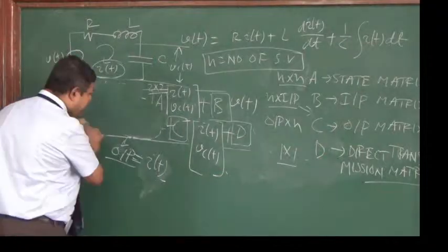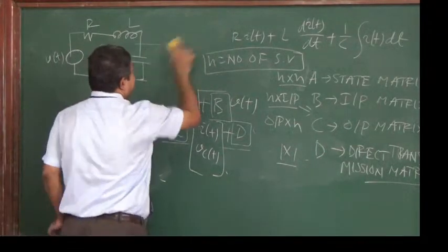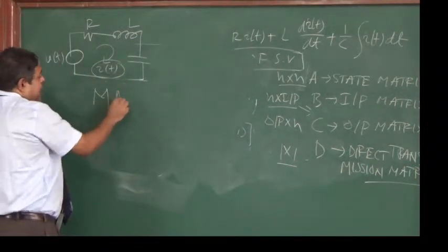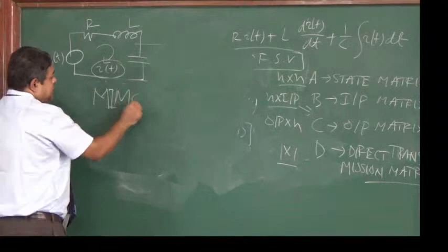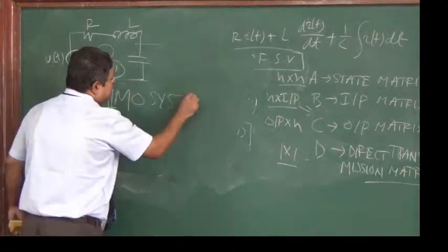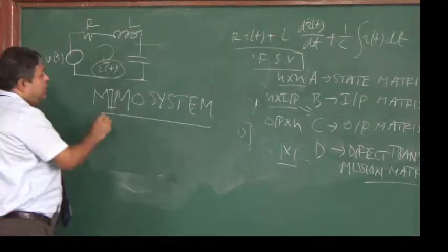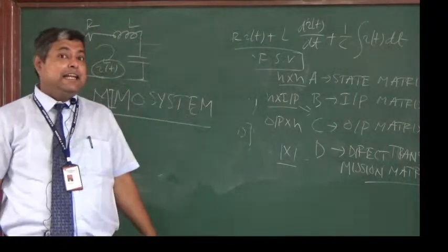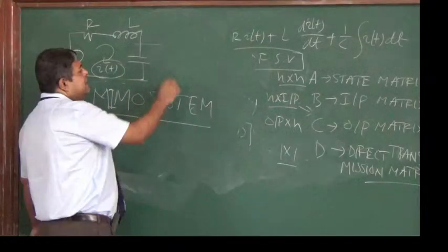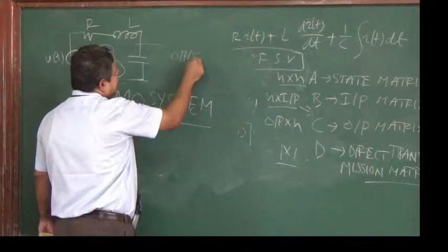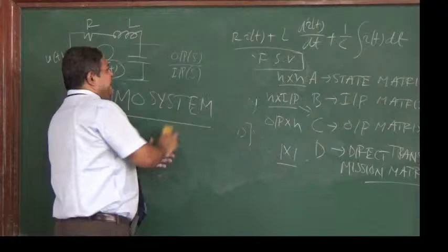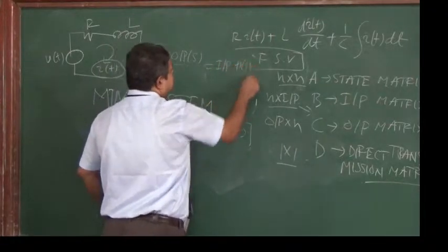One very big advantage of the state variable system I did not tell you: state variables can model what is meant by MIMO. It is called multi-input and multi-output. If you remember yesterday's models, we took some output quantity Laplace divided by some input quantity Laplace, and this was the transfer function.